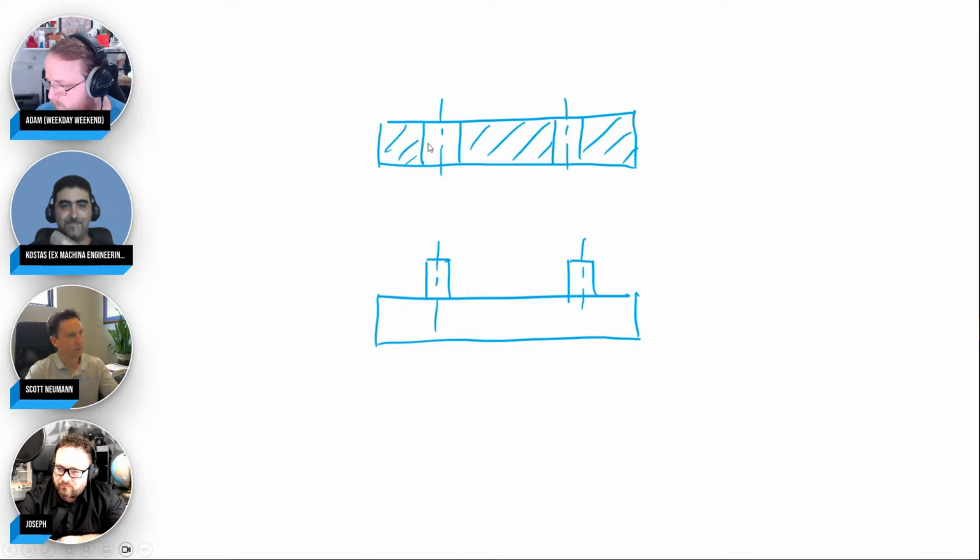How do I make sure that these holes will not be off position too much where they accept the pins? And it's real easy. Smallest hole, biggest pin. And then when you do your position tolerances, we say the tolerance zone always applies the length of the feature. So you get a cylindrical tolerance zone on this one, you get a cylindrical tolerance zone on this one. Now, when you insert that pin into the hole, the tolerance zones overlap each other. So it's just a really easy smallest hole, biggest pin, split it between the parts. It's simple.